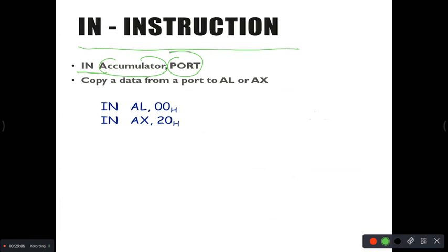Hope you remember when you are typing the program, I know you are blindly doing copy and paste. In the first few lines you have written port address of port A, port B, port C. And there is one more control register, where you program your 8255, the programmable peripheral interface. That's what this port address is.